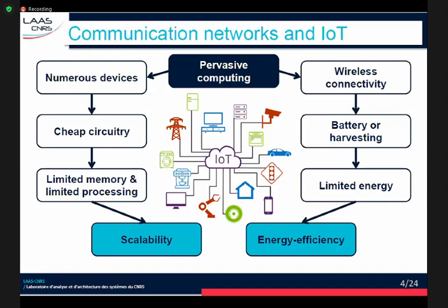At the same time, since we are speaking about IoT, billions of devices potentially, we don't want to put a cable to connect each of them for communication. We also don't want a cable to power them with current, so they should be standalone devices. This means we need wireless connectivity. That in turn implies battery-operated devices, which also use energy harvesting. Of course, this puts a problem of limited energy. So we should care about energy efficiency.